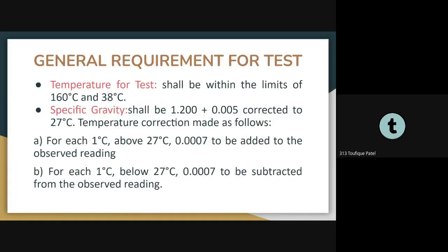Now, general requirements for test. First one is temperature for test. The temperature for test shall be within the limits of 16 degrees centigrade to 38 degrees centigrade. Second one is specific gravity. Specific gravity shall be 1.2 plus or minus 0.05, corrected to 27 degrees centigrade.